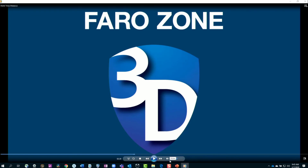So my next question, Mr. White, is those momentum animations look great. They're automatically created. So why would we need to create an animation over and above the one that's already created for us? Well, the animation tool is an analysis tool. So while it's very helpful in determining speeds and providing other information, the automatically created momentum animation doesn't allow the customization like intermediate vehicle positions and damage profiles.